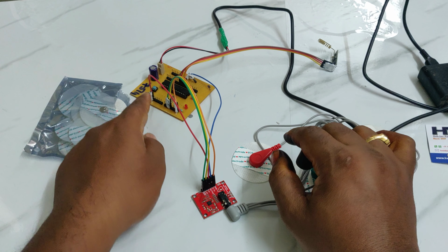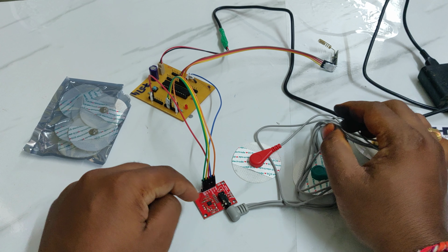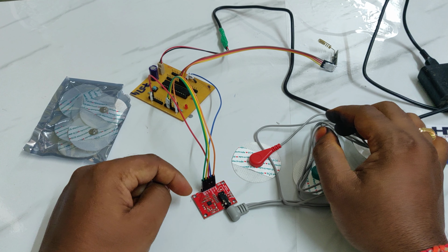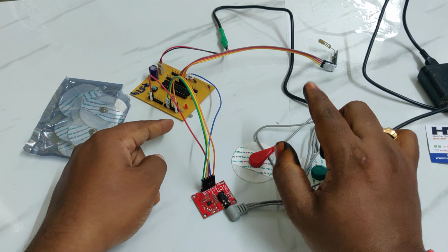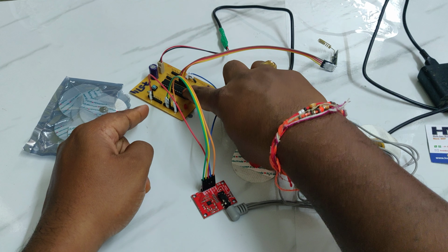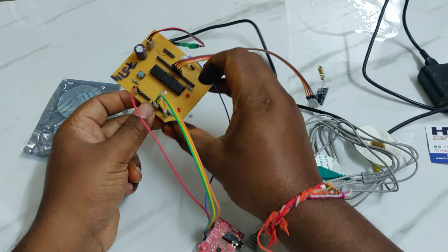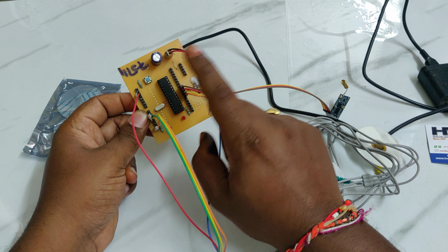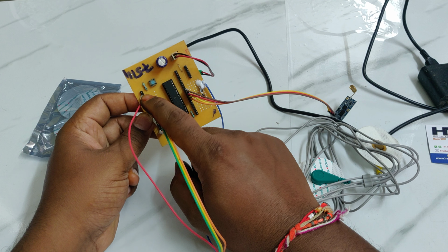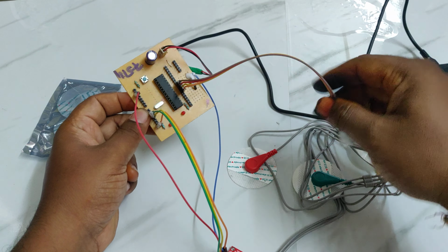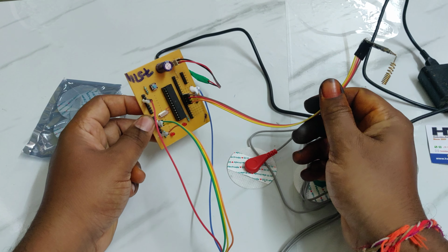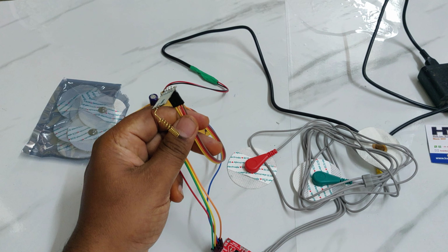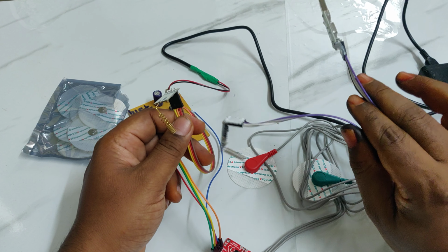And the next, A0, to get the ECG readings, that is nothing but the analog voltage readings, and that will be converted into serial using this PIC16F72 microcontroller. We are using the PIC board which is used to convert this analog signal to a digital, serial signal. So this signal will be transmitted to the receiver section which will be connected to the MATLAB. This is a laptop screen.